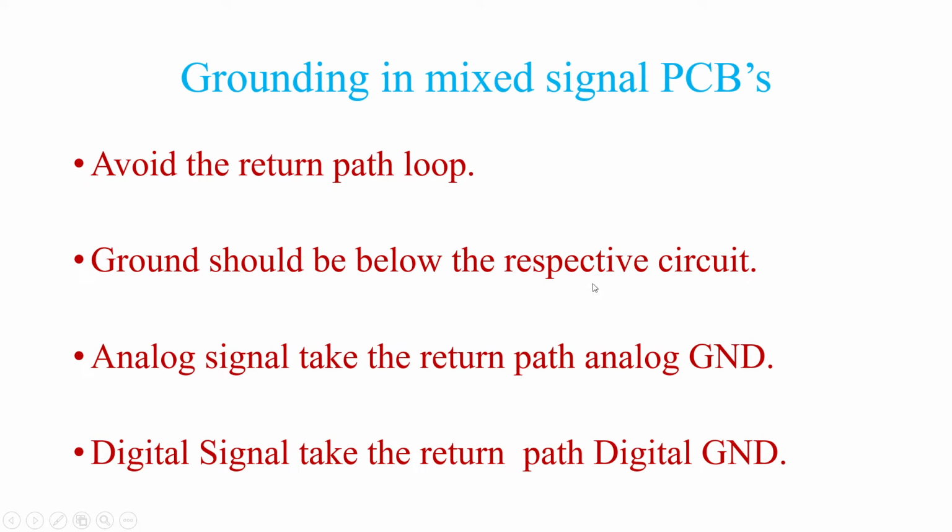Ground should be below the respective circuit. Analog signals take the return path through analog ground. Digital signals take the return path through digital ground. The high-speed PCB designer has to keep this in mind while designing the PCB for mixed signal.